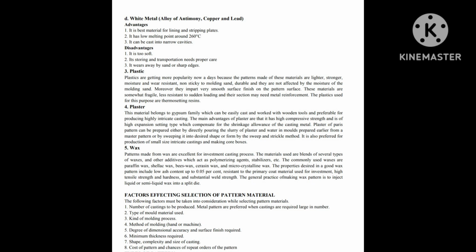Factors affecting selection of pattern material. The following factors must be taken into consideration while selecting pattern materials. 1. Number of castings to be produced. Metal patterns are preferred when castings are required in large numbers. 2. Type of mold material used. 3. Kind of molding process. 4. Method of molding, hand or machine. 5. Degree of dimensional accuracy and surface finish required.